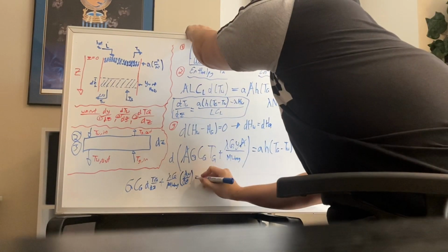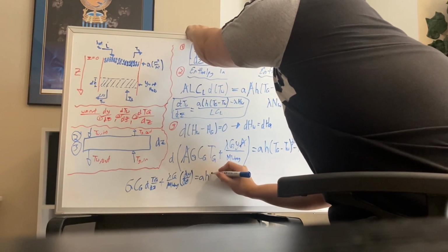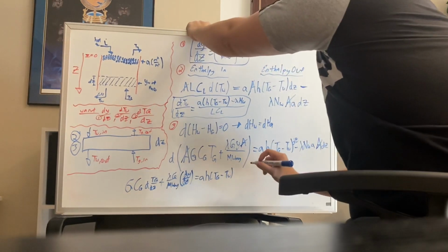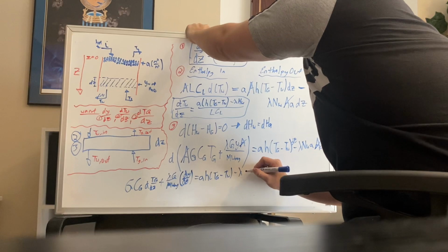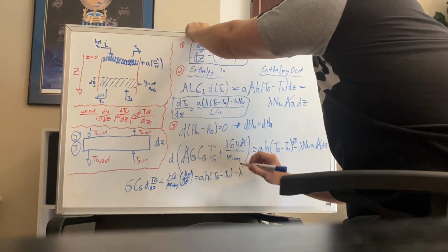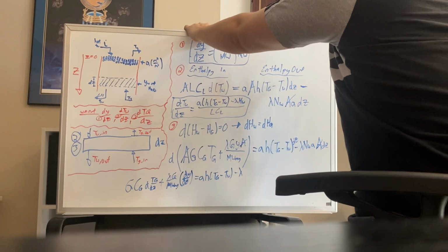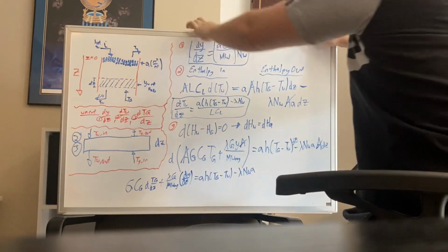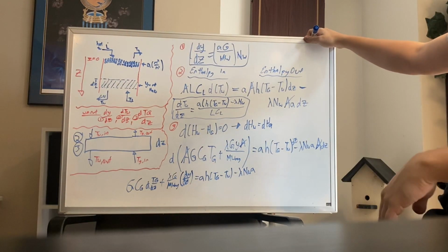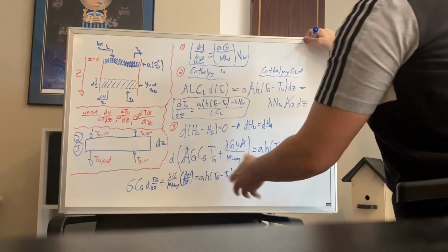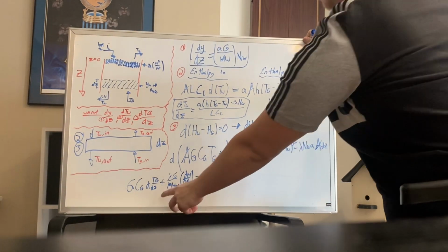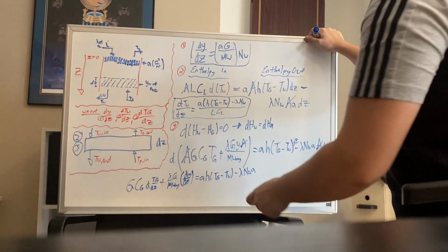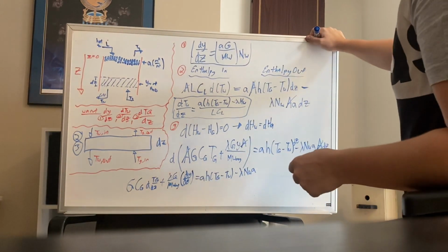of the equation, which is going to be equal to specific area multiplied by heat capacity multiplied by the differential in the temperatures between the gas and the water, minus the heat of evaporation constant multiplied by the molar flux of water multiplied by the specific area again. And so now this is a lot prettier than what we have up here, to be honest, because we have this dTg/dz, which is what we desire to get for our last differential, but we also have this dy/dz that's included right here.